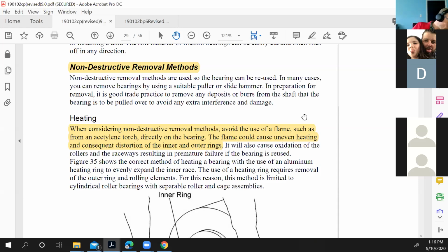Good one. One is like a hanger bearing. Yeah, hanger bearing. I usually cover it with a rag and then smoke it with a hammer and let it crack, and then I have to torch off the other side. You got to be really good with a torch. Yeah, I can talk about steady bearings or hanger bearings as well. They're a good example of that, absolutely.